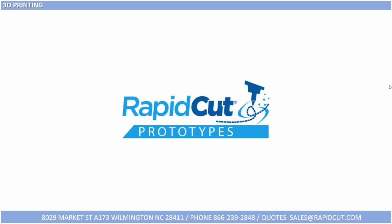Okay, yes, so we do get a fair amount of requests for using 3D print as master patterns. An example of that could be an SLA master pattern to create a urethane tool from which you're going to make a series of parts, a short run. Another example would be an investment cast, where we would take an FDM. It's got a water soluble material available that we can build a part out of, and then slurry that part, creating a mold. Then we pour hot water in, it melts out the FDM pattern, leaving the cavity that you can then cast metal into. So that would be an example of using these processes for patterns.